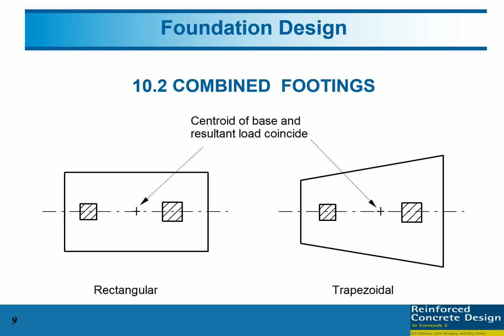If there is no constraint on the length, people will use the rectangular. But for example, if the location of this foundation is at the border with other people's land, there is no choice, we need to shape the foundation based on the border line.